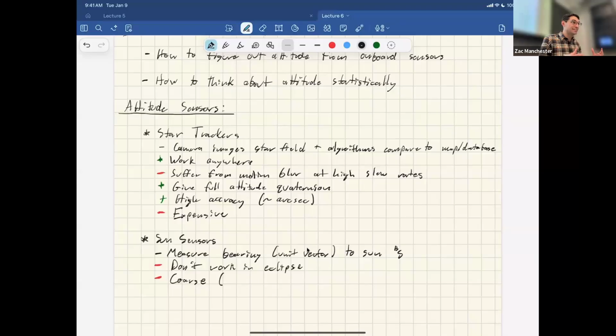There are also dedicated sun sensors of various kinds. There are simple ones with a single photodiode on a face, where the sun vector is related to the cosine of what you see. And then the fanciest ones are little pyramids with a bunch of photodiodes on various faces, and these give you the most accuracy. Those can be sub-degree, but in general these things are on the order of a degree or two.